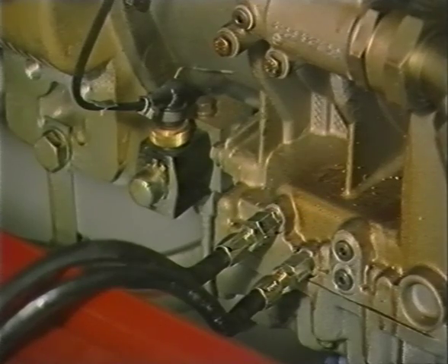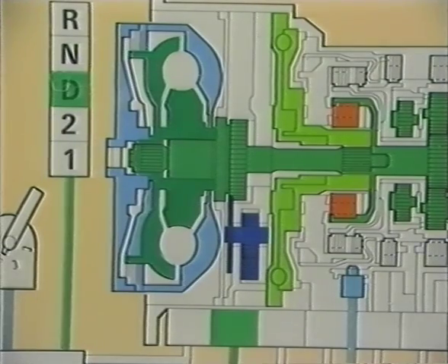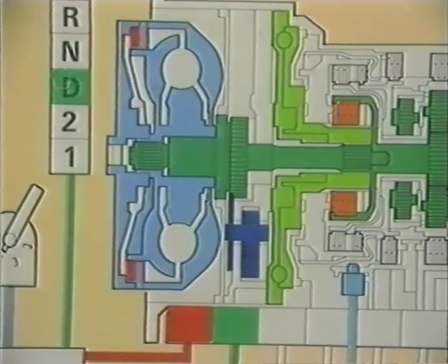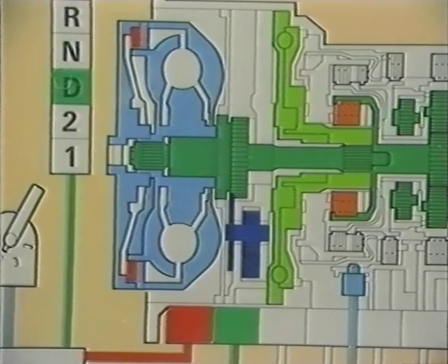You will recall that when the torque converter is in operation, the main oil pressure is at 18 bar, and when lockup takes place, the pressure drops to 10 bar. If the gearbox operates continuously with the converter unlocked, this will increase the operating temperature of the gearbox. On the assumption the correct pressure response takes place, the converter is operating correctly, and the main vehicle cooling system should be inspected.